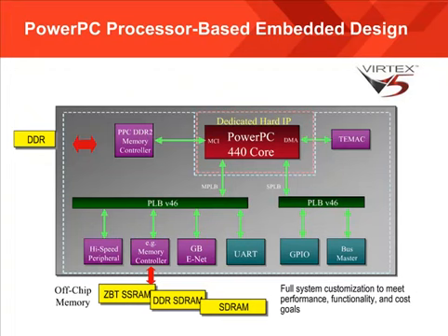Now, often customers will ask, well, how fast can the system run? That will depend on the number and the size of peripherals, as well as the number of buses that you add to your system. Specifically, again, this boils down to how many LUTs and registers will be required for your entire embedded system, and that will determine how fast each bus will run.